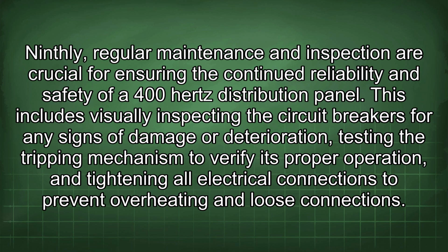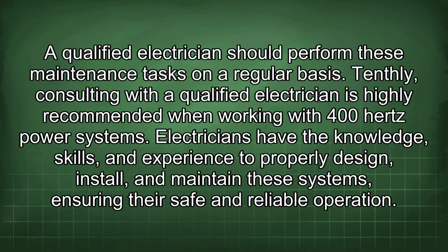Ninthly, regular maintenance and inspection are crucial for ensuring the continued reliability and safety of a 400 Hz distribution panel. This includes visually inspecting the circuit breakers for any signs of damage or deterioration, testing the tripping mechanism to verify its proper operation, and tightening all electrical connections to prevent overheating and loose connections. A qualified electrician should perform these maintenance tasks on a regular basis.